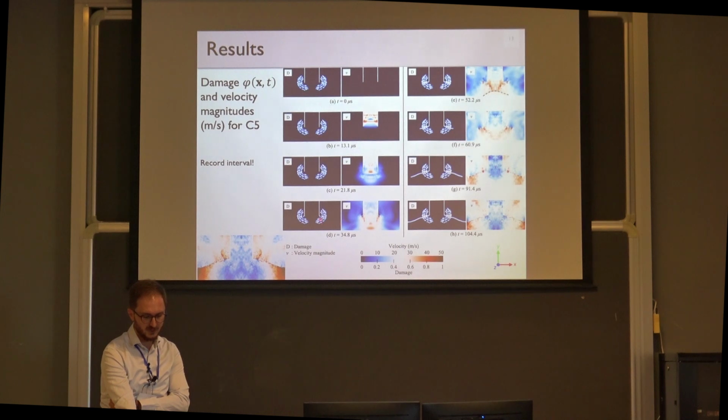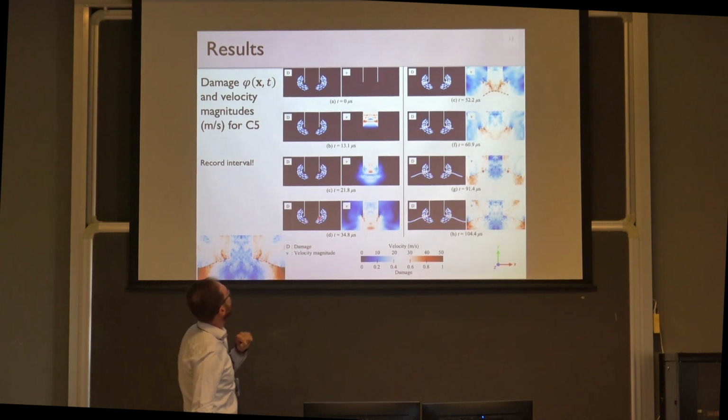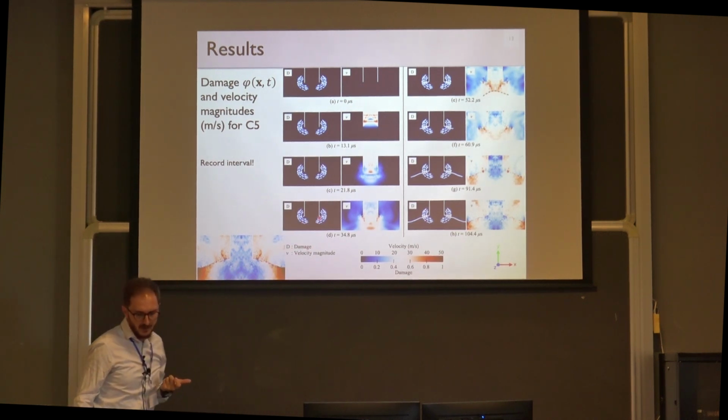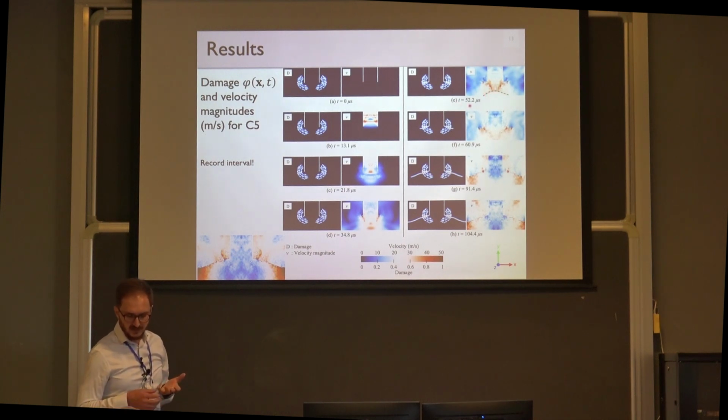The crack starts to propagate here. There is a small crack propagation here. At this point, there is no crack initiation yet. And then we have a reflection wave coming from the bottom of the body, and we can see this wave here. I drew a dashed line to see this reflection wave properly at 52 microseconds. And after that point, the reflection waves mix with the compressional waves, and actually the kind of mode transition starts here.